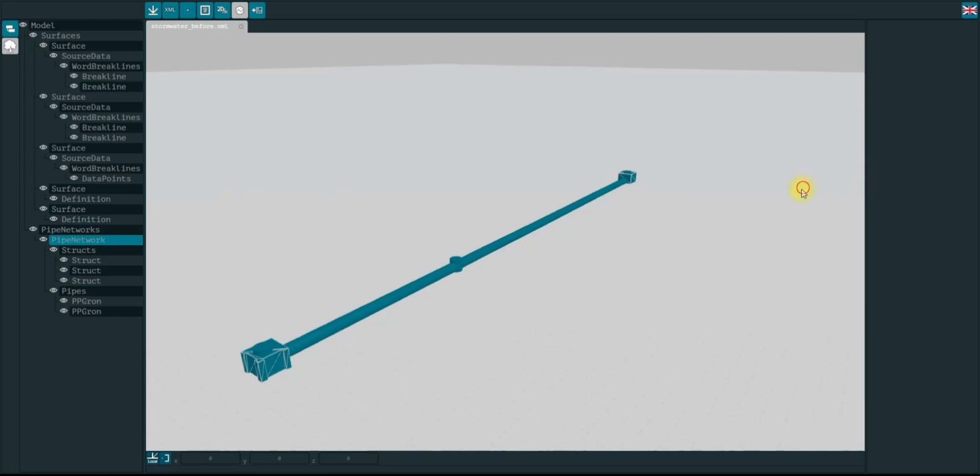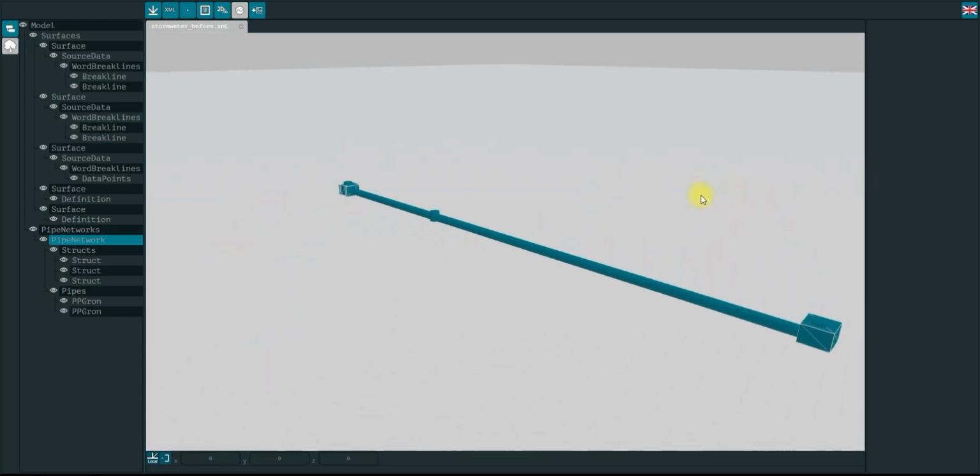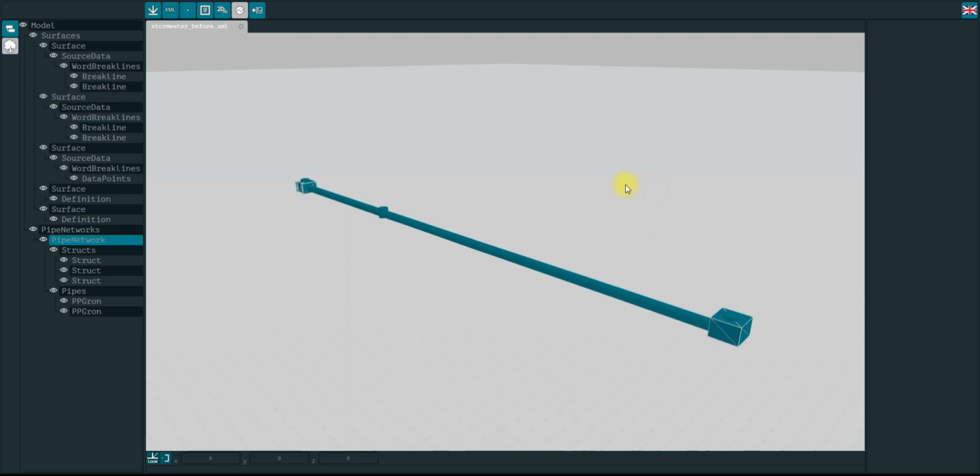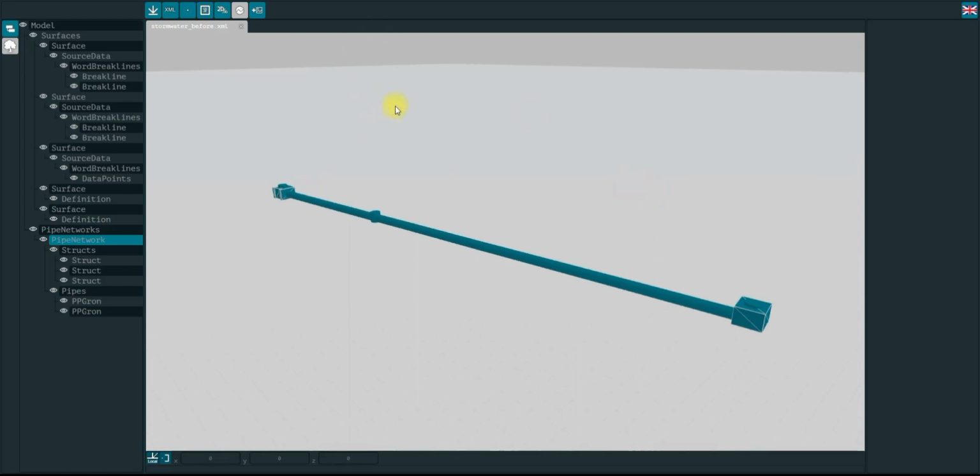Then before we go any further, there's a few things you might want to check to make sure that your model is completely functional and compatible with other platforms. So first of all, you might want to go through all the objects within your model and make sure they all bear a different name. Like if they do not, you might want to just rename them manually.